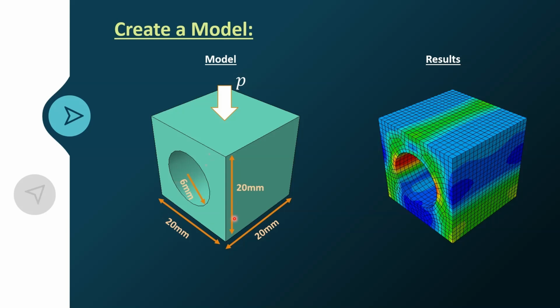So we have five parameters in total, and for these parameters we are going to create variables, so that we can change these variables and run different models with different values. So this is more like a DOE kind of study. DOE stands for design of experiments, wherein you change certain parameters required for the analysis, and find out which combination is the most desired one or the optimized one. So those kinds of things we can do once we build the script to do the analysis, right?